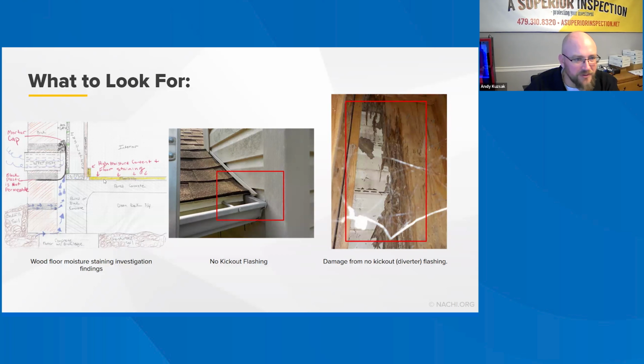And so they kept calling the builder. The builder had no idea what was going on. I was called out to investigate, and we were able to take out a row of brick next to a weep hole. And then this is what we found. We found the 6 mil poly. The painter actually painted in the weep holes, so there wasn't even airflow going through the weep holes anyway. And then the brick masons, so much mortar fell down the backside into the air gap that it actually created a mortar cap on top. So the only airspace that the weep holes, if they weren't painted, the only one that they were transferring air from is in this small section here.